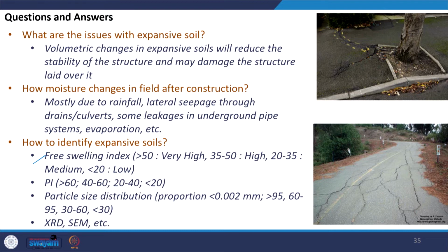In this free swelling index, let us say we take 10 gram of soil, okay, and we will put it in say 100 ml of water, and then again what we will do, we will take similarly 100 ml of kerosene here, and here also we will put a similar amount of soil, okay, and then we allow this soil to change its volume, and we will condition this specimen, and after the conditioning period we will see how much change in the volume has taken place.